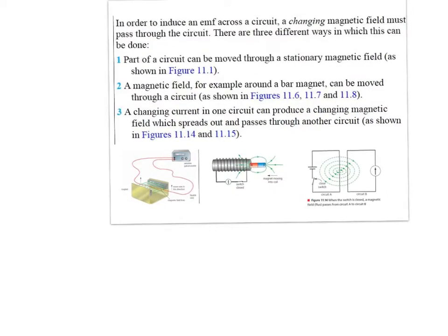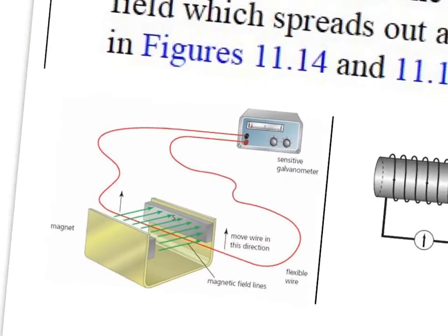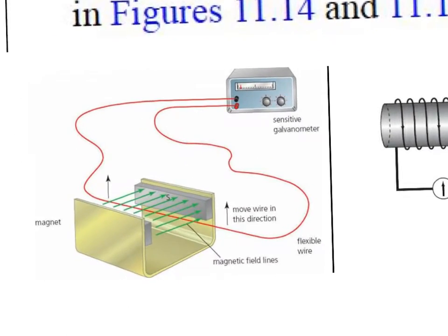Well, when you're moving a conductor inside a magnetic field, or the other way around, what you're doing is you are cutting the lines of flux. So in this example, you are moving the wire in an upwards direction, and the wire is gently cutting an area of flux lines. You can always visualize the wire literally breaking up these green lines, cutting the lines of flux. It doesn't really matter how that happens. What's important is that the lines are cut, because it's the cutting of the lines that creates the EMF.